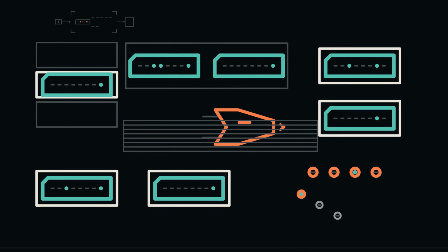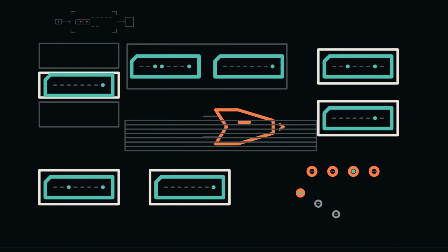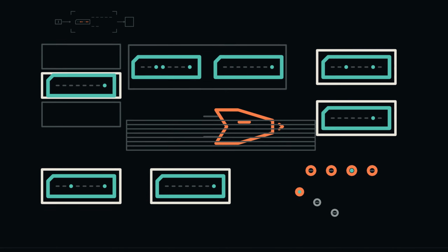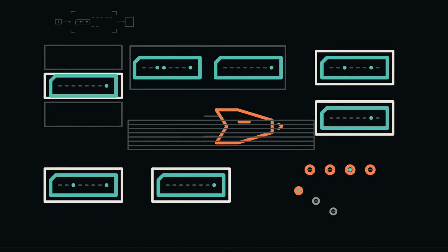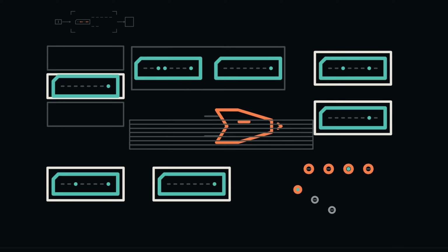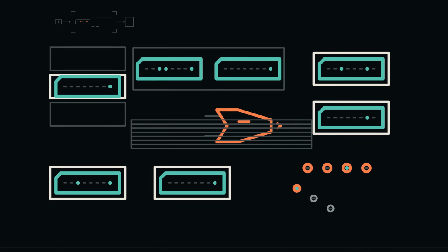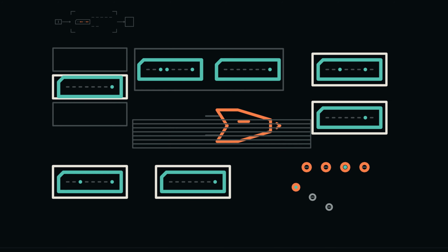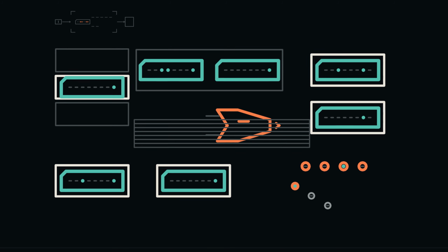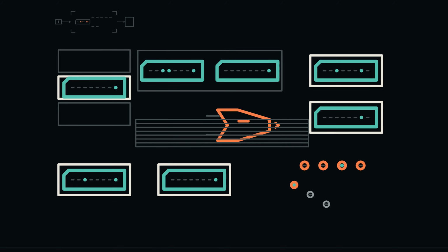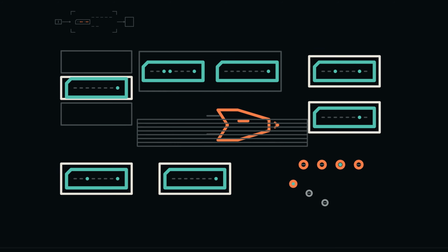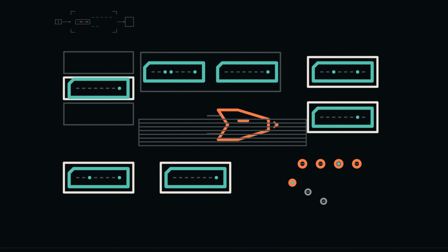Predict the final edge. R0 captures 2, zero remains clear, negative remains clear, carry becomes set, and overflow remains clear. PC remains 22 because subtraction does not alter control flow. Memory remains unchanged. The controller marks the instruction complete, increments its instruction index, resets the per-instruction microstep index, and returns to fetch 0 address.